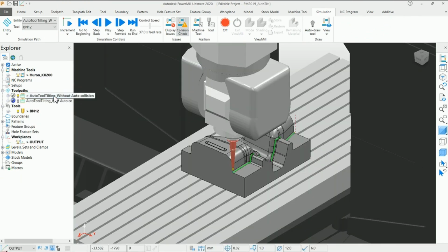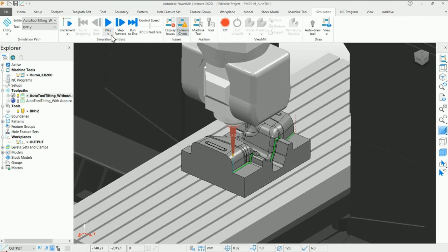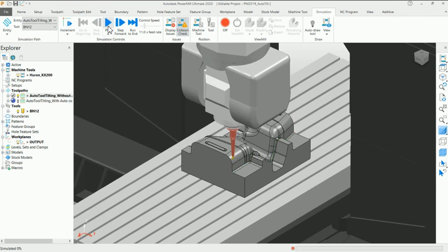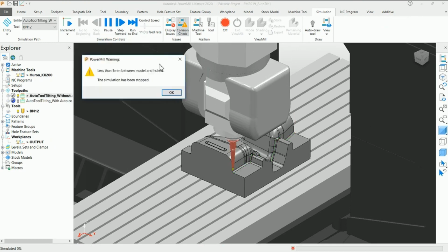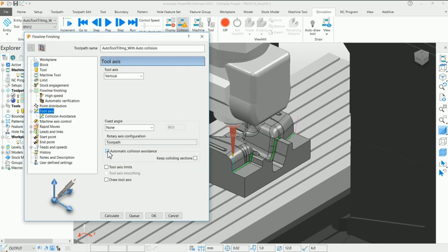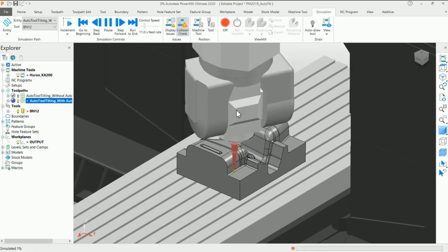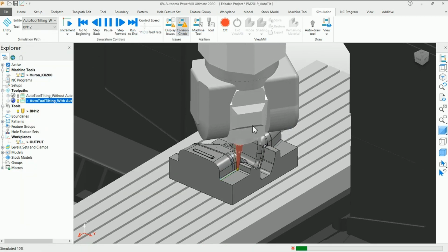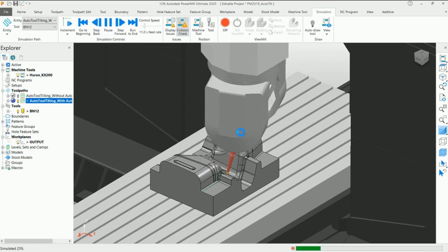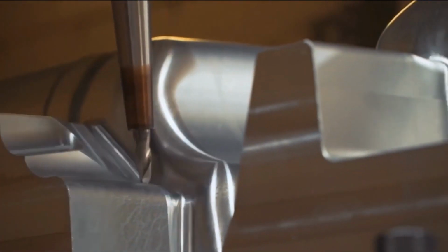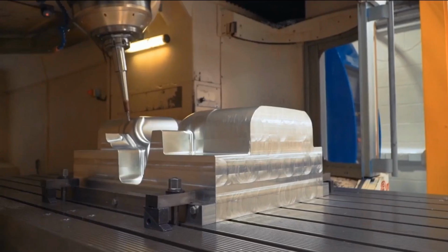Automatic tool axis tilting can be used alternatively, with a wide range of tool axis tilting options within PowerMill. It produces continuous 5-axis toolpaths without any collisions, with a significant reduction in programming time. Additional blend control improves the machine motion even further to increase surface finish accuracy.